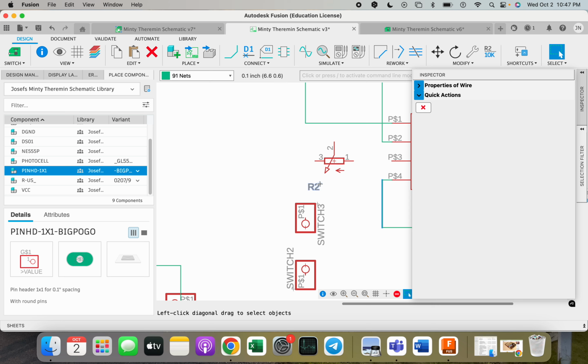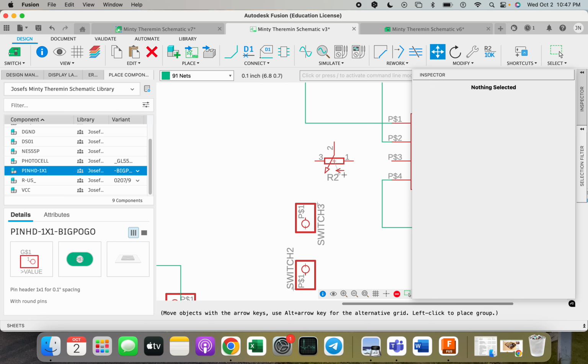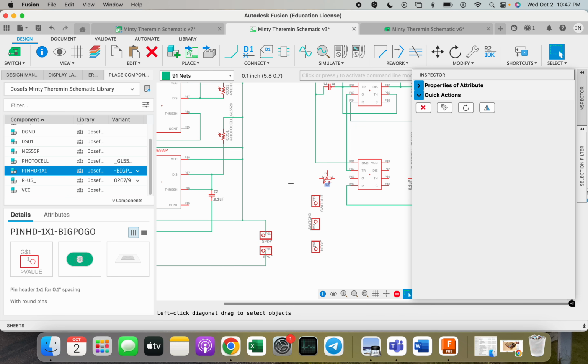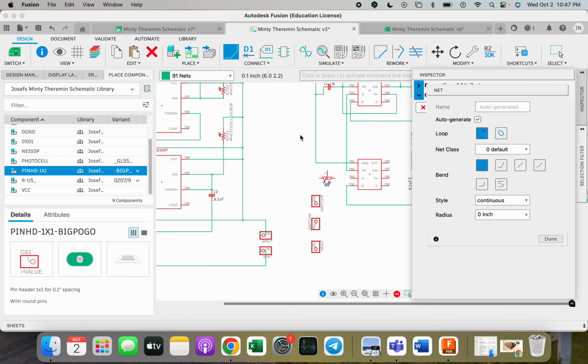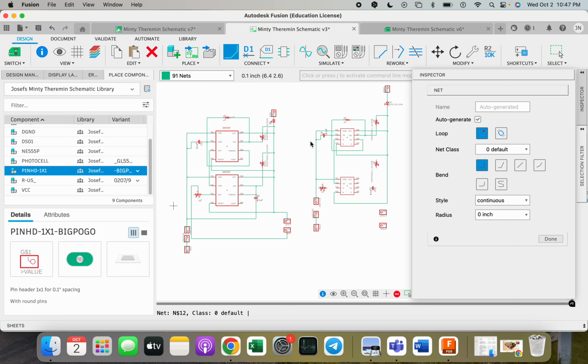You'll notice this label here. I'm just going to move that back over there. Now going back into my net command, I'm going to grab from this point down to my switch, and then from my switch to the negative. You'll also see we said we want to carry on with number 1, all of the connections. So pin 1 on the lower 555 is connected around to capacitor 2.